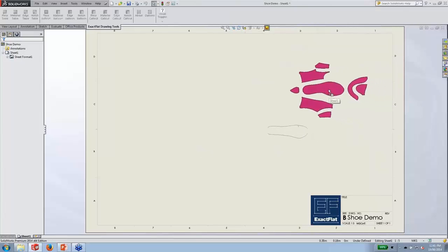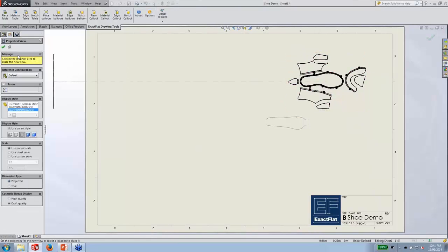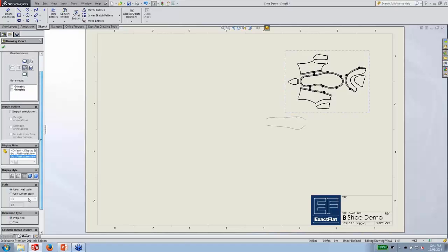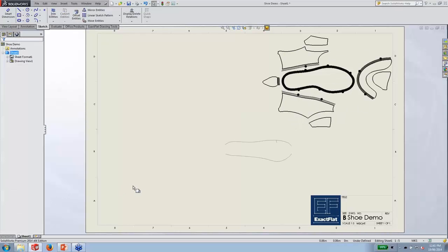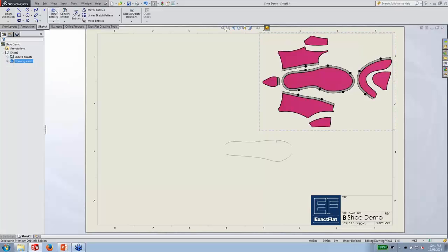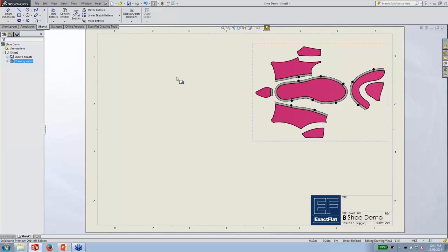So this is how we do it. We start with a template, a SOLIDWORKS drawing tool template. You could customize it, or you could use one of the standard ones that are available. You take your pattern pieces and you literally drag them into the document template. Here we're using a B block. We do support other sizes depending on your industry. So for example, if you use A, C, D, or even E size drawings, that's not a problem here.